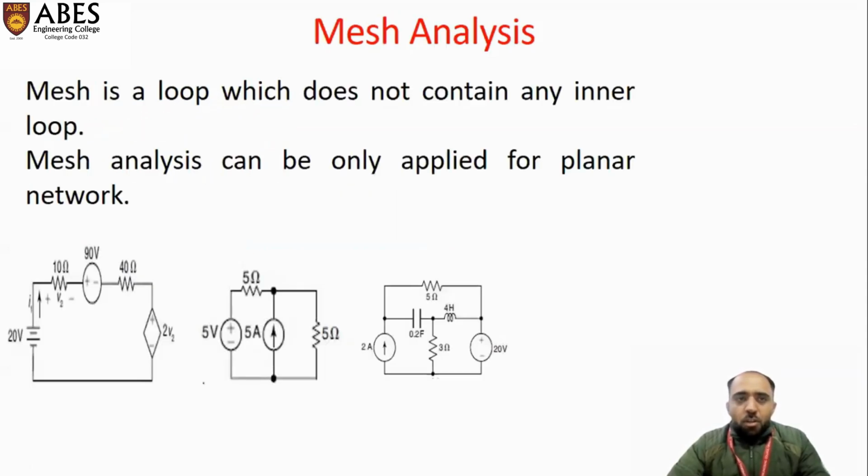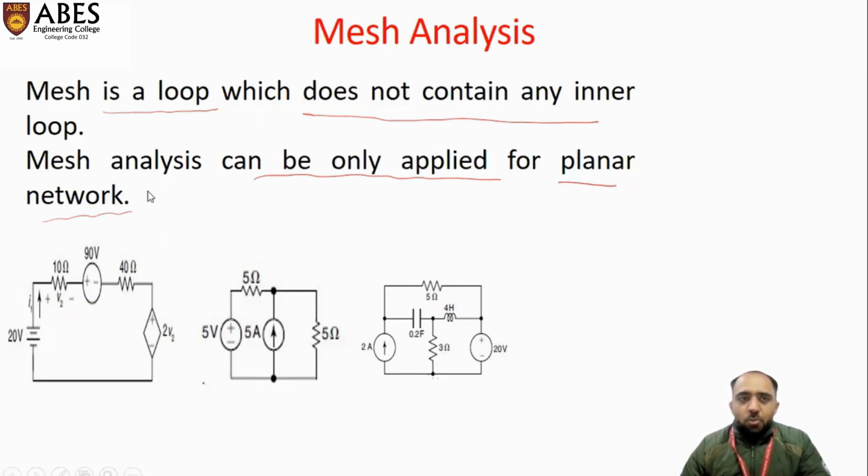So let's talk about what is mesh. Mesh is a loop which does not contain any inner loop. So this is the basic definition of the mesh. Also, mesh analysis can be only applied for the planar network. If we want to find the current or voltage across any resistance in the circuit, we can use the mesh analysis. So first of all, let's talk about what is mesh.